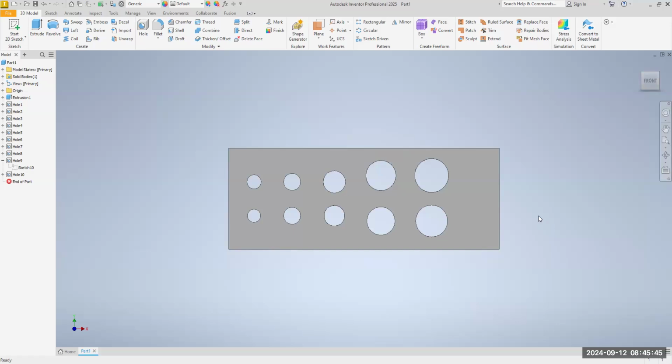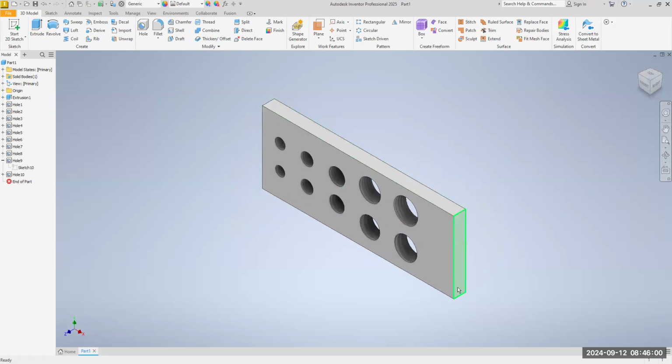There's our holes. Now, if you look at our drawing, do we have rounded corners? We do, right? That's called a fillet. So we need to round this corner, and this corner. Do not round this one. There's a reason why we're leaving that a sharp 90.